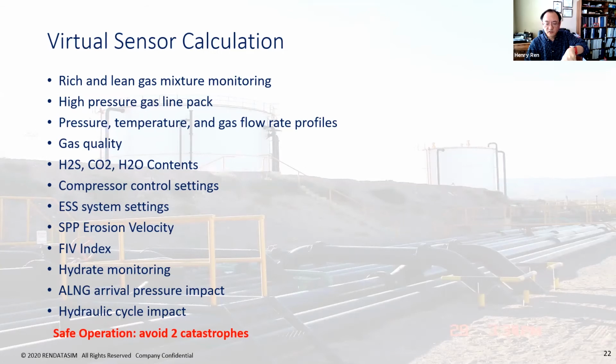So the manual valve is green, but the temperature downstream goes down and upstream goes up. Then we built some kind of logic and said, maybe you need to look at this. And the coordinator in the control center caught it at that moment and called the platform to avoid the potential disaster.